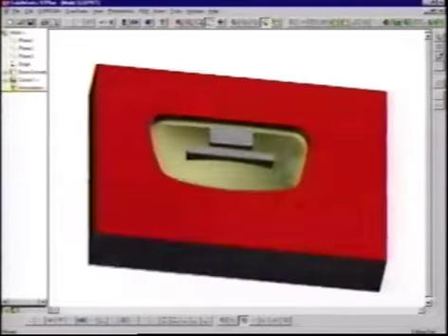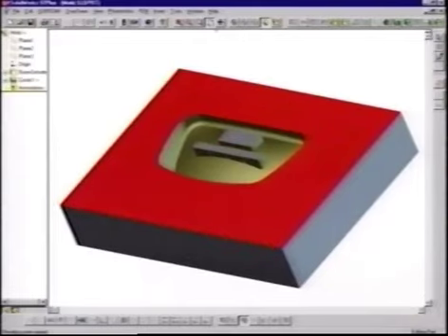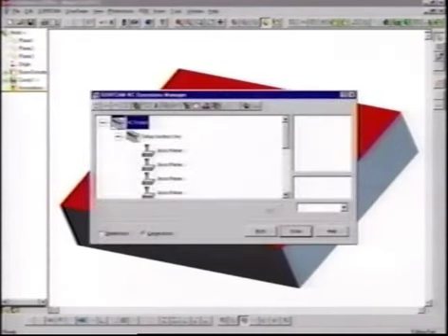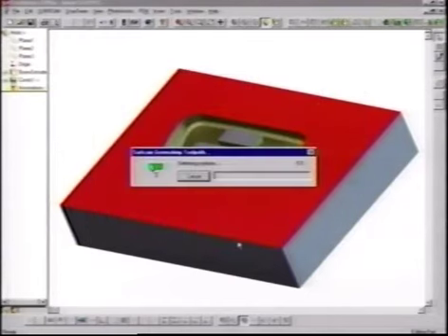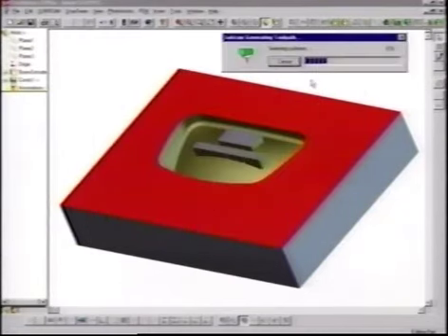And what about the manufacturing operation? Remember, Joe generated that toolpath with not a SOLIDWORKS application, but an integrated third-party application. But you know what? Those are fully associative as well. So as he selects on it with the right mouse button, you'll see he has a regenerate toolpath option. What SurfCAM is doing right now is it's reevaluating the SOLIDWORKS geometry that it machined earlier. It's found out that there's a change, and it's now generating a brand new toolpath based on the modification made there. And when it's done, you're going to see the toolpath follow the brand new contour created by Joe.